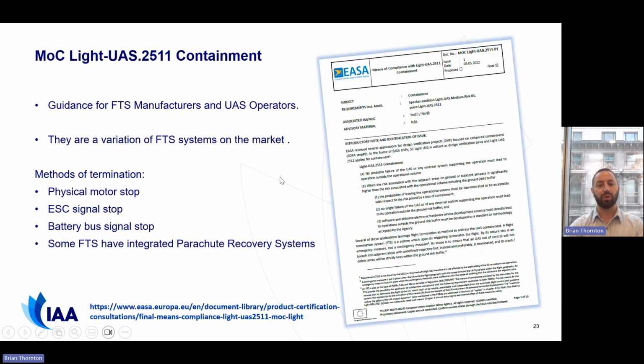Now, we move from enhanced containment requirements within 947, the extant regulation, and we'll talk now about the link to MOC Light UAS 2511 Containment. This is the publication, so you can see it on the right-hand side. It's available on EASA's website, and you can see the link below. This is guidance for FTS manufacturers and UAS operators. There are a variety of FTS systems on the market. You might say, well, we've jumped directly into FTS. So what does FTS mean? FTS means Flight Termination System.